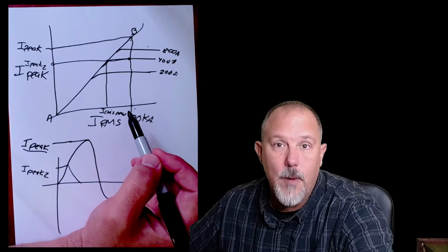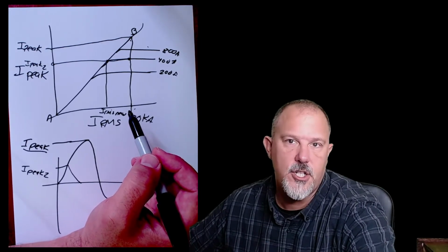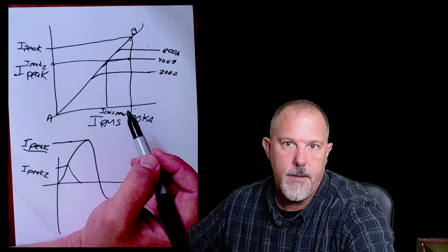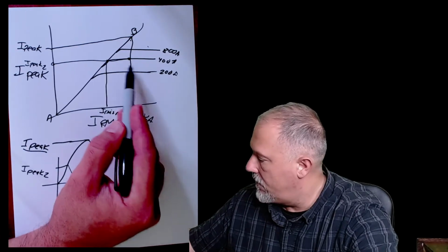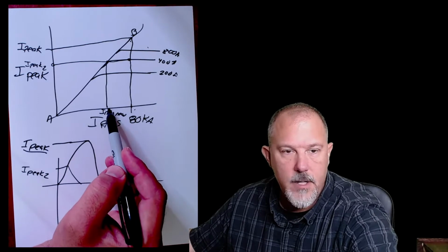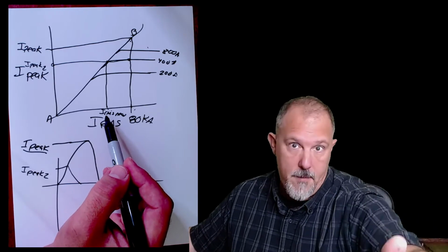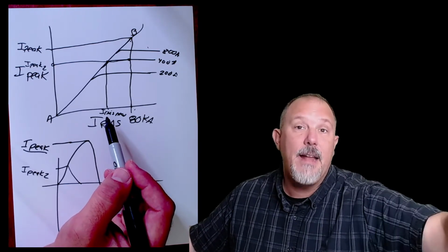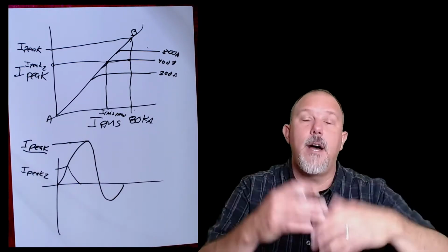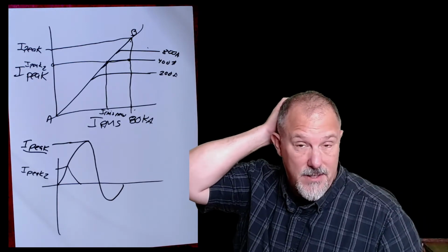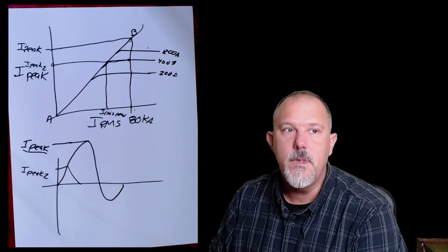Think about what we rate, say a busway, and say the busway has, without overcurrent protection, a 5,000 amp short circuit current rating. And I have 80,000 amps of available fault current. If I go up, over, and down, if this new RMS value is less than 5,000 amps, then I can say I'm protecting that bus because the fuse is not letting as much RMS through. That makes sense. Now, I can do that on things like busway that aren't dynamic.